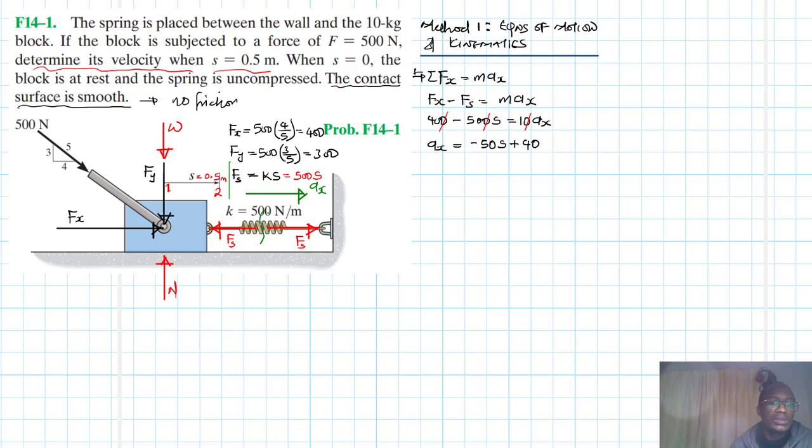All right, so let's then apply the kinematic equations. I'm going to use this derived equation, which is just ax ds is equal to v dv. And this comes from the two equations, v is equal to ds/dt, remember velocity, and a is equal to dv/dt, right?